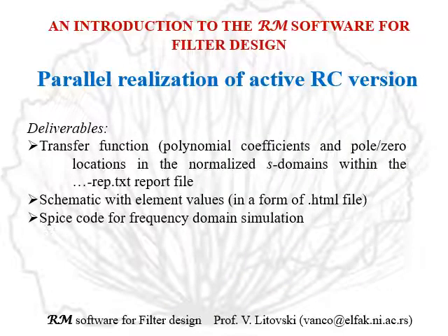Here the deliverables are also a report file containing the whole process of the synthesis, the .html file which contains also the schematic, and SPICE code for frequency domain simulation. Since it contains only linear circuit elements, by simple modification of the excitations and the simulation type comments, one may produce a time domain simulation by the same file with not much effort.